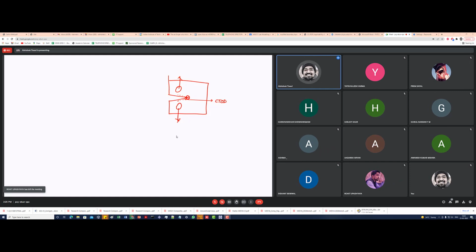Usually if you look at this volume, this ligament is going to be much larger than this zone, right? We have established in theory of elasticity that it should be at least 50 times the plastic zone radius. But for J integral it will be even smaller. The plastic zone will be even smaller.